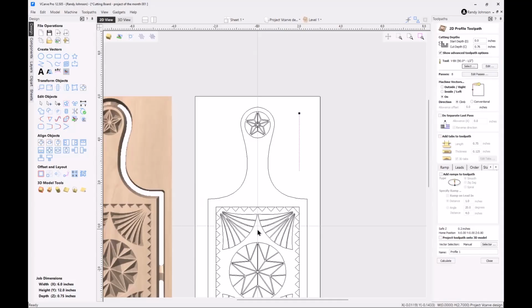And so if you're starting out, you're going to use these toolpaths, come to understand the difference between these two toolpaths in particular. The V-carve toolpath is a decorative carving toolpath, specifically made for doing that decorative carving, whereas the profile toolpath, the best way to think about that is much more like a handheld router or like a bandsaw or a table saw where you're following a line.